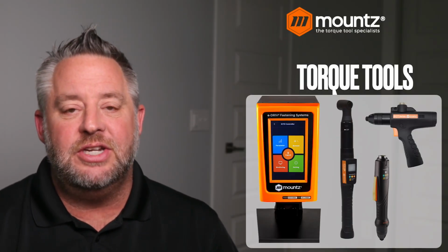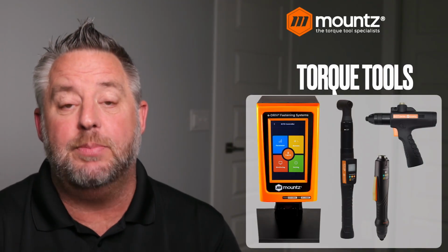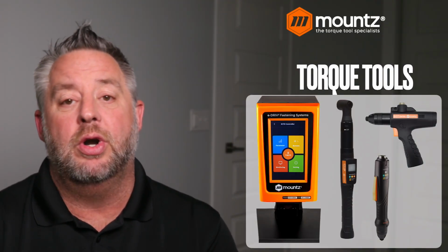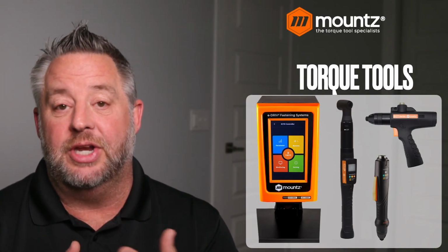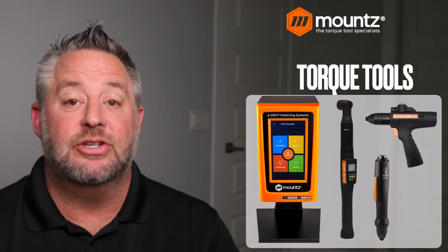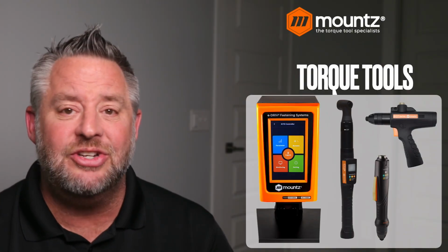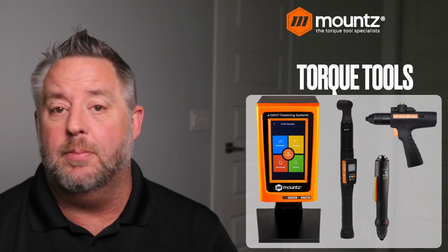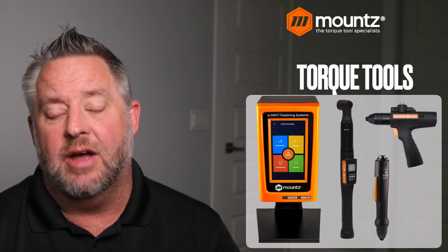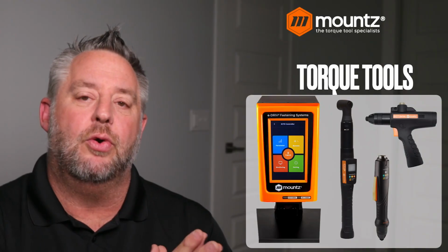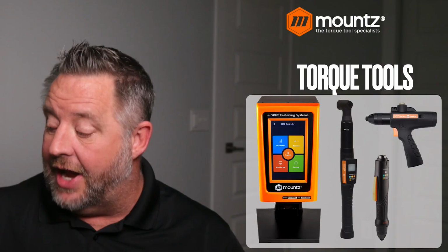The DC tool is a more expensive type of application, but more and more it gives us a lot of control, a lot of flexibility, and a lot of traceability as it relates to fastening. And these go from very, very low inch-ounce settings up to 50 Newton meters in most cases for these types of tools, with different orientations such as right angle, inline, or pistol grip style of tool.